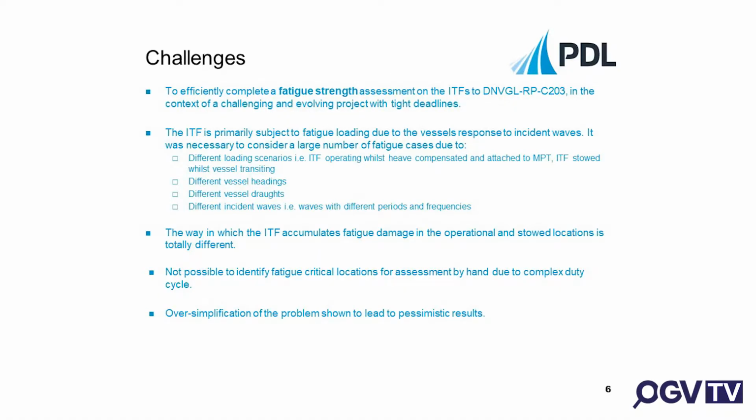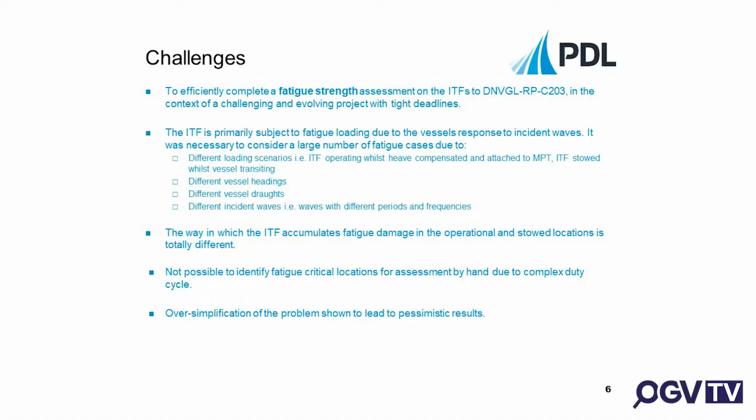So what are the challenges when you're completing a high cycle fatigue assessment on these kinds of structures, the ITF? I guess the main challenge, which many of you are probably familiar with, is that the main loading this is going to be subjected to is due to the vessel motion. So due to waves hitting the vessel, it rolling around and then being accelerated.